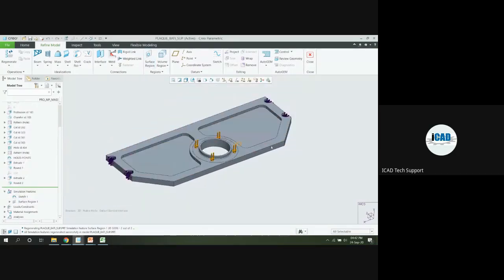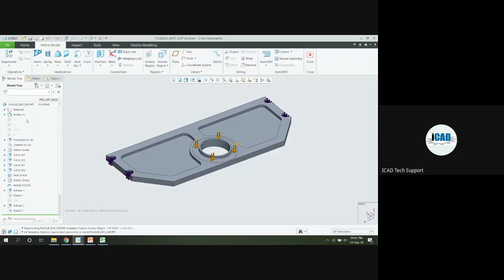So during simulation, the software automatically calculates the element size, using the auto geometric element option. We can also control the element size by using maximum element edge length, minimum edge length, hard point, and hard curve.